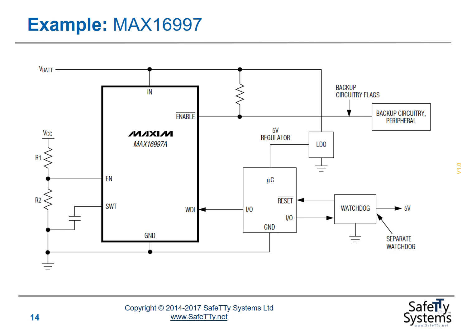So here's an example of an off-the-shelf component that might be used to implement an EWDC. This is a MAX16997 device. So this is our microcontroller. Just to emphasize the fact that the EWDC is not itself a watchdog chip, this design has a separate watchdog component incorporated in it. You may or may not require such a device in your design. It's not an essential component here. But it emphasizes the fact that this is not functioning as a watchdog timer.